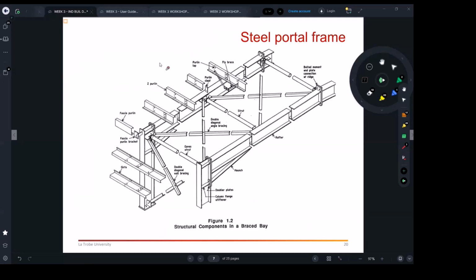If you look at this image, these are the purlins, and your sheets will be running the same way here. These are the sheets, the green color. It's up to your transportation, they can go between 6 and 8 meters. They're also going to be lapped with the next sheet you have there. We will not practice the span tables, but how to decide on the size of the sheet is going to be similar to what I will show you for selecting girts or purlins.